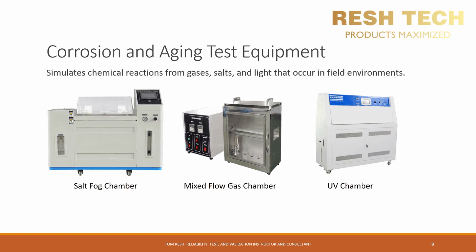A UV chamber or ultraviolet chamber simulates exposure to sunlight and is used to accelerate aging of materials from UV light. You would be amazed at how difficult it is to not have fading or bleaching and/or cracking occur with certain colors and materials. So keep that in mind and test early when you are looking to select cosmetic or even critical parts such as seals that will be directly exposed to ultraviolet light.